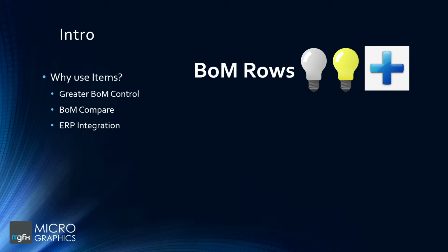We could switch rows that were potentially switched off back on. Could be things like packaging material, shipping crates. You can also then use the option to add extra bill of material rows. So we could take the bill of materials as it would be in Inventor with all the CAD designs, but add packaging, add those other items that are not drawn in Inventor.